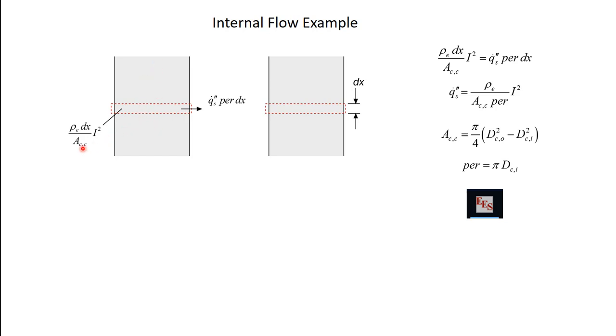So my only in is whatever ohmic dissipation, whatever thermal energy generation I have inside this control volume. That's the electrical resistance of the control volume times current squared. The electrical resistance is the resistivity times dx, the distance I have to move the current, divided by the cross-sectional area of the conductor material. So that's I squared R.